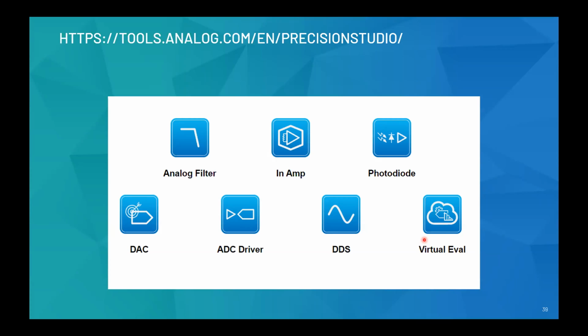Then you have the DAC driver tool, which would tell you what post circuits you need in order to make sure that your circuits are driven correctly. We have the ADC driver tool, which helps you play around with the different choices of fully differential amplifiers at the front end and make the correct choices. We do have the DDS source generator and the virtual eval to do a virtual evaluation of the ADCs, rather than really waiting for an eval board to come.